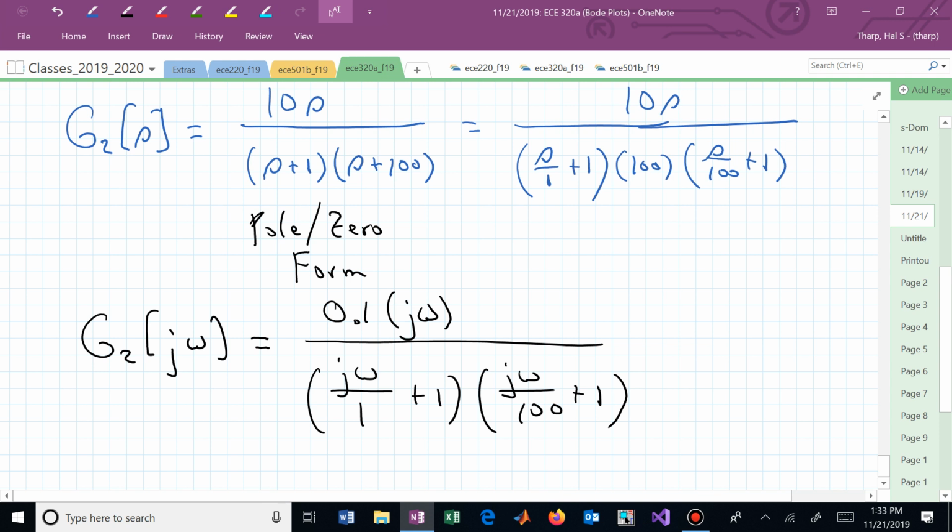What does that give us? That's now coming up from the bottom and going up all the time, plus 20 dB per decade. If we took 20 log of j omega, that's just 20 log of omega, and we're plotting with respect to log of omega. So that goes up and it crosses 0 dB at what frequency?